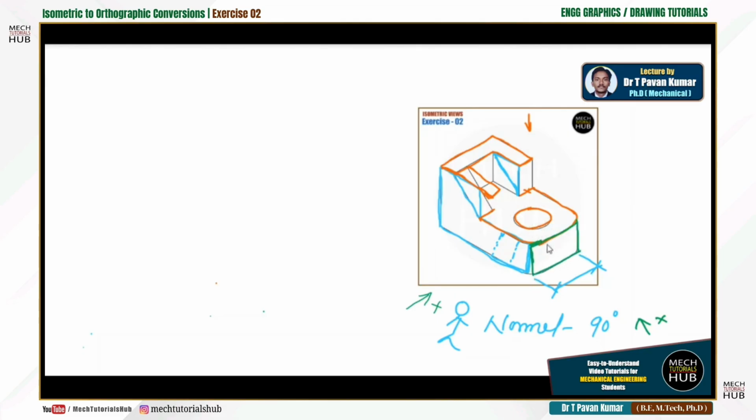Similarly, you know that there is a circular hole in the center, so you can keep it as a hidden line, because as you are viewing from here, the existing circle is known by the observer, but it is not directly visible to us. So we need to show it with invisible edges, followed by this slant edge again visible like a reduced vertical edge, followed by this vertical edge. You can feel this edge exactly at this point. Similarly this box is also visible to you. This line is colliding with this back vertical.